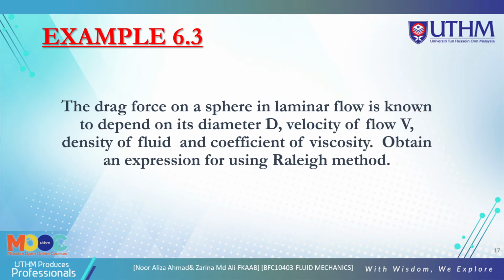So now look at the example here. The drag force on a sphere in laminar flow is known to depend on its diameter d, velocity of flow v, density of fluid, and coefficient of viscosity. Obtain an expression for it using the Rayleigh method. So using the Rayleigh method, the parameters in this question are the drag force, the diameter, the velocity, and also the coefficient of viscosity.